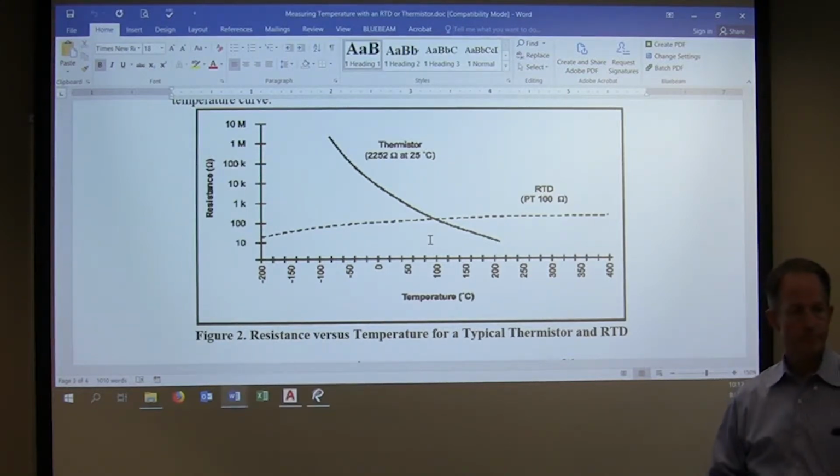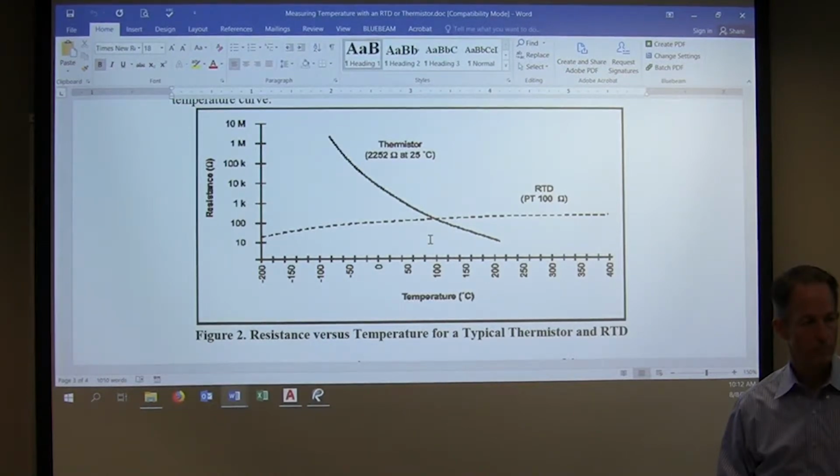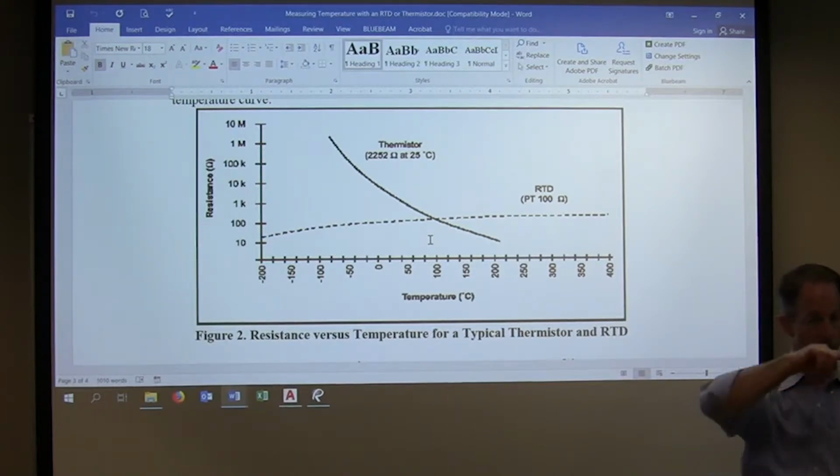Thermocouple for temperature. Okay, thermocouple. How does the thermocouple work? It's a bimetal, two metal wires, and wherever they're soldered together, that's the junction of the joint, and then when it's exposed to heat, it generates millivolts. So heat causes an electric current to flow.